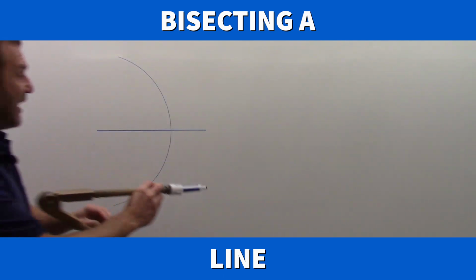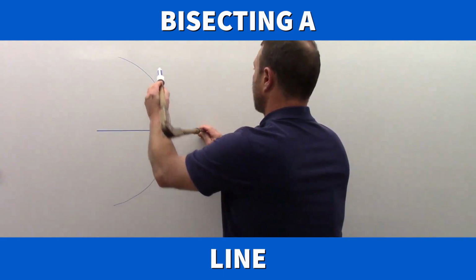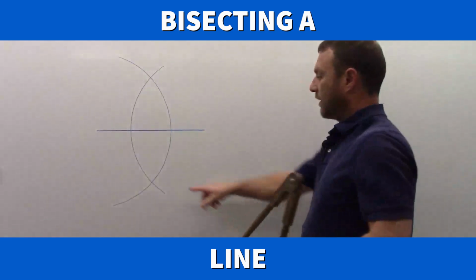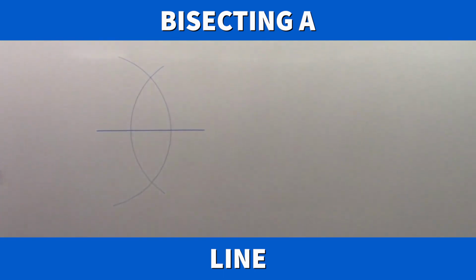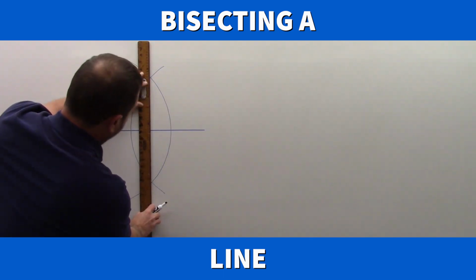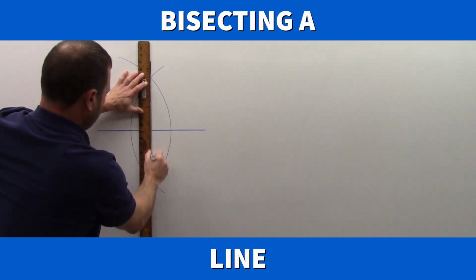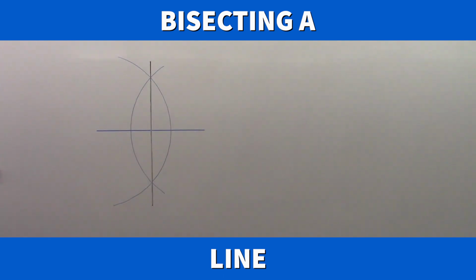And keeping that same distance on my compass, I come to the other side and swing an arc here. Now what we're looking for is the 2 cross points. And if we connect those 2 cross points, they will break that line exactly in half. And that's bisecting a line.